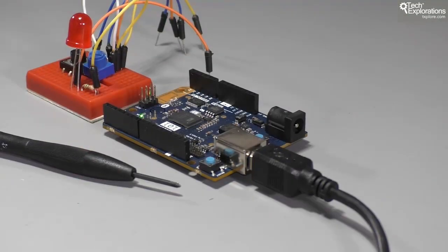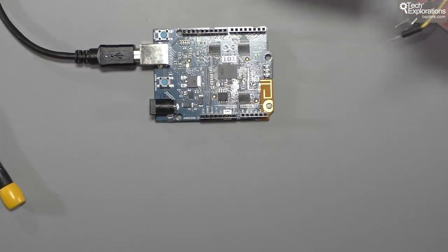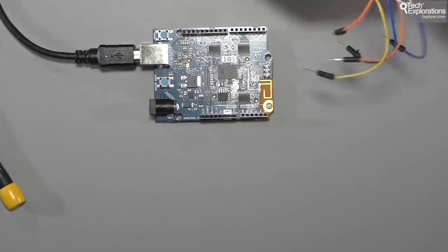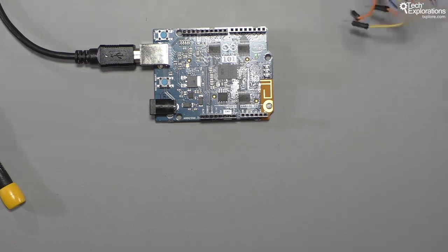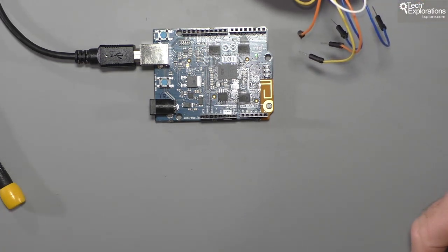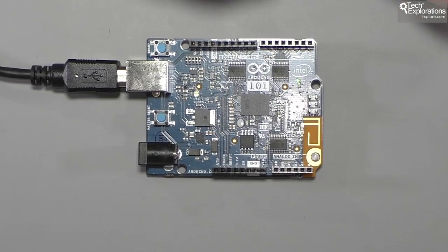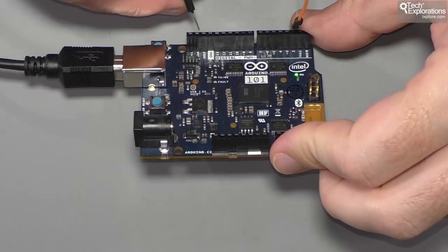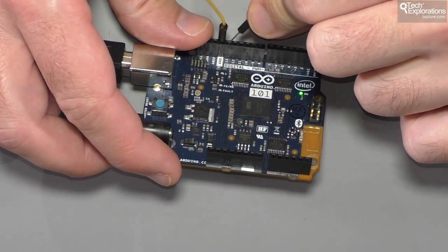Okay, so I will first connect the LED. I'm just going to clean up my breadboard here so that it's not too cluttered for this example. I'll be using the button and the potentiometer in a follow-up example in a minute. So this is a cathode. I'll plug that to ground, and the anode will go to pin 13.